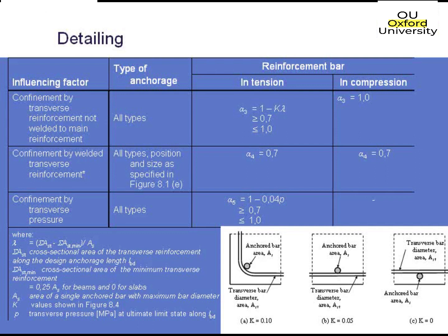You're better off just using the same anchorage length or lap length throughout the entire structure, and using these clauses as justification when things aren't done as they should be on the site. It might also be an area where, if you have a discussion with the contractor, they might want you to start applying these, and then you'll have to make sure that they are actually applying it on site, because it is a very big potential error for fixing reinforcement on site. It's very easy to get it wrong if you've got lots of different anchorage lengths and lap lengths throughout the structure. The guys fixing the reinforcement are just going to get it wrong, basically.